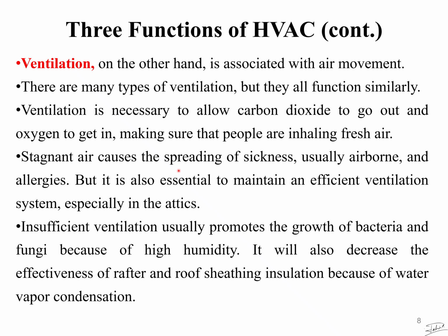Stagnant air causes the spreading of sickness, usually airborne, and allergies, so it's also essential to maintain an efficient ventilation system. Insufficient ventilation usually promotes the growth of bacteria and fungi because of high humidity. It will also decrease the effectiveness of rafter and roof sheathing insulation because of water vapor condensation. So ventilation is also important for maintaining fresh air in the manufacturing area.